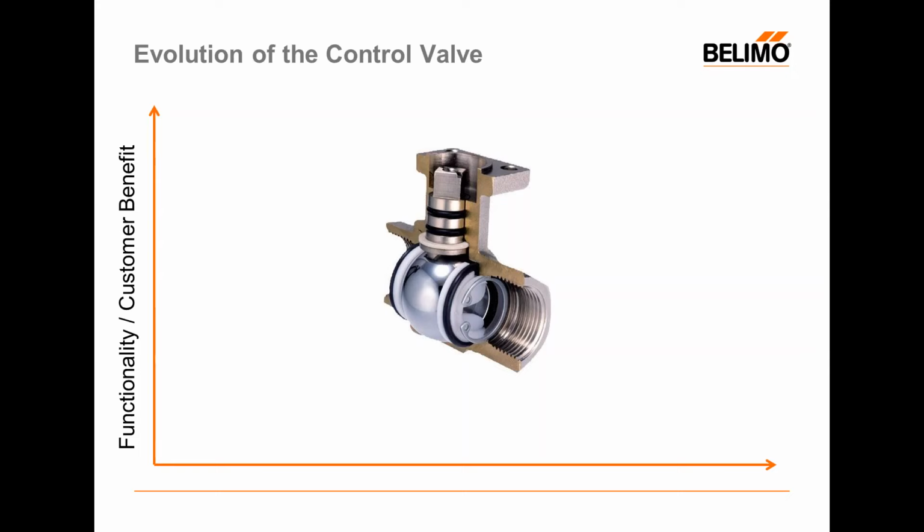control valve. The reason we call them position control valves is that the control signal drives the actuator, but it is only driving the position of, in this case, the rotating stem. If I give it a 50% control signal, it's going to rotate the stem 50% of the way and create an opening through which the water needs to pass. However, we can all agree that if I have a specific opening and there's 1 psi of water pushing on that opening, I'm going to get a dramatically different flow rate than if the same opening saw 50 pounds of pressure. Now granted, that's a humongous swing.